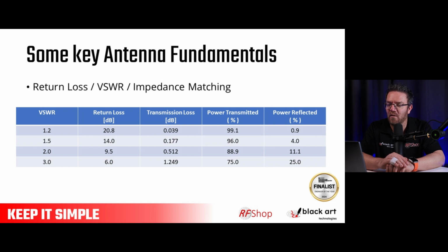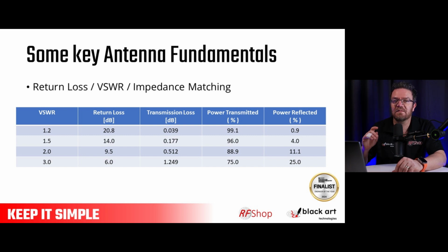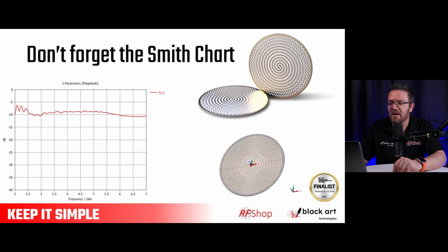But if you reach 2 to 1, often people say, yeah, you know what, this is getting close to the best we can achieve. So between a 1.5 and a 2 to 1, that is what normal antennas can do. If you look at the dishes that they use for astronomy and so forth, definitely that's much better. 1.2 is almost absolute worst case, and then you go even better. So it is technically possible, in the very high-end and specialist, to go way better than 1.2 to 1 as well.